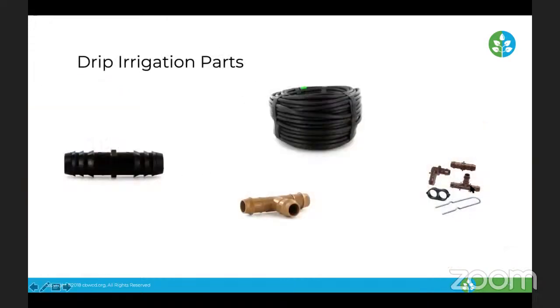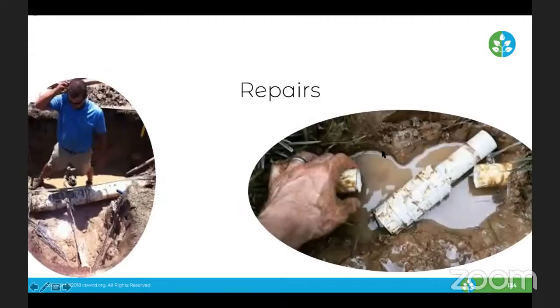So really quick, these are the components for the drip irrigation system. So you can see we do have the T fittings, we have the 90 fittings, we have the couplings, but you notice that they're not glued, they're insert fittings. So they have barbed components that go inside the drip tubing and will not come apart. Again, that's why it's essential to have that lower 30 PSI rating.